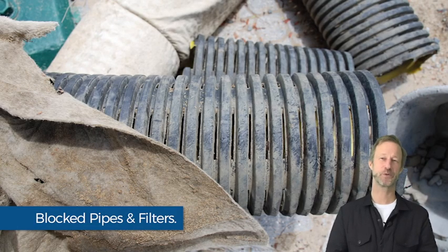This photo shows the drainage assembly from an actual job site. An inspection of the pipe confirms it is in good condition with the slots clear. The cause of the failure is the filter wrapping the pipe completely is blocked by fine particles. Filters work when they're new, but from the moment they're put in service, they deteriorate in efficiency as they block particles until they become completely blocked.